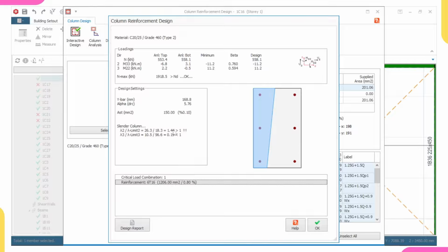So slenderness is just a ratio of square. It means that your column should be more of a square for it not to fail in slenderness. And also remember, let me explain something. Columns fail in two ways. We have two types of column: a short column and a long column. A short column fails by crushing, that's squashing. It's just as if you crush something or squash something. A long column fails by buckling, and it is from that buckling that the long column gets its slenderness ratio. So a column failing in slenderness means that you should increase the size of that column.